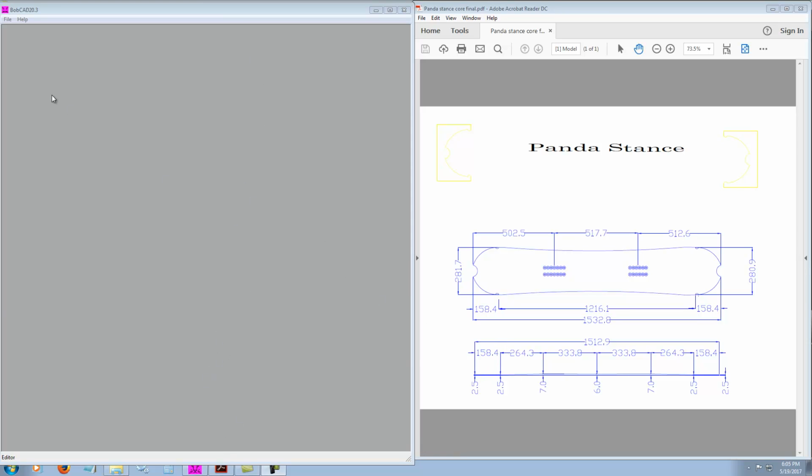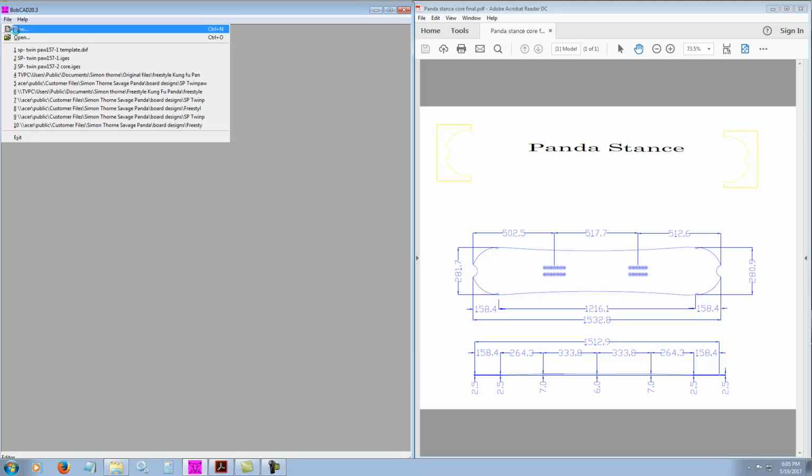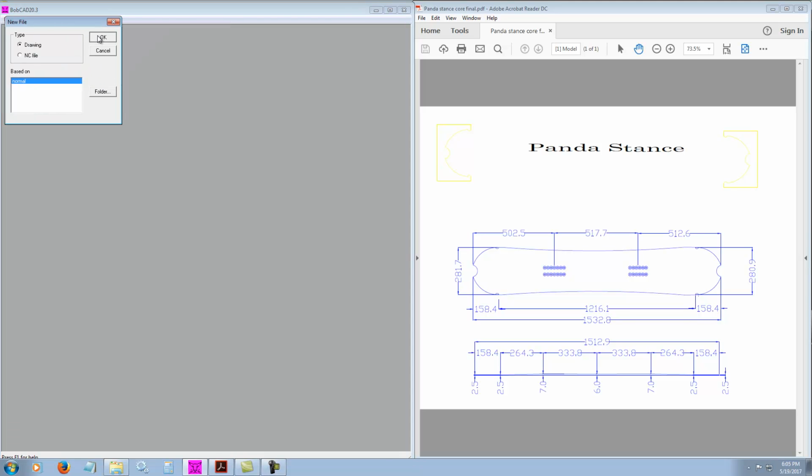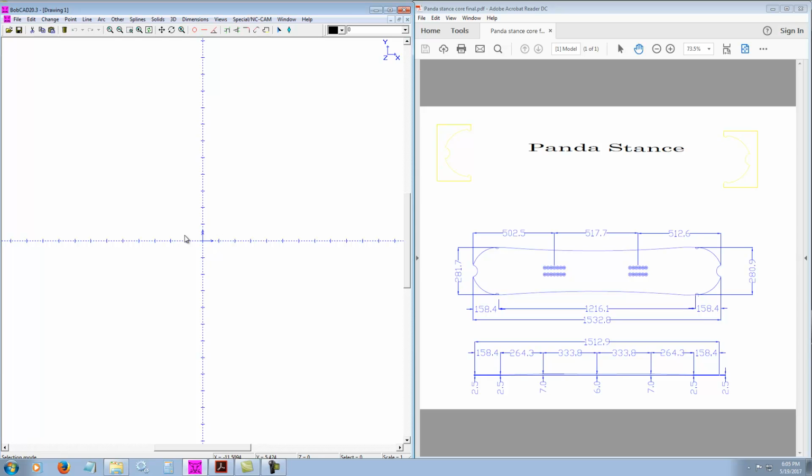So what we would want to do first is go File, New, and select Drawing, and that just opens a blank drawing with 0, 0 axis right here. We're going to basically draw a rectangular core that goes like this, assuming this bottom left corner is the left-hand rear corner of the CNC router, and we're going to place a core blank on it, and then we want to mill it out so it has the variable thickness going back and forth like the mouse is doing here.